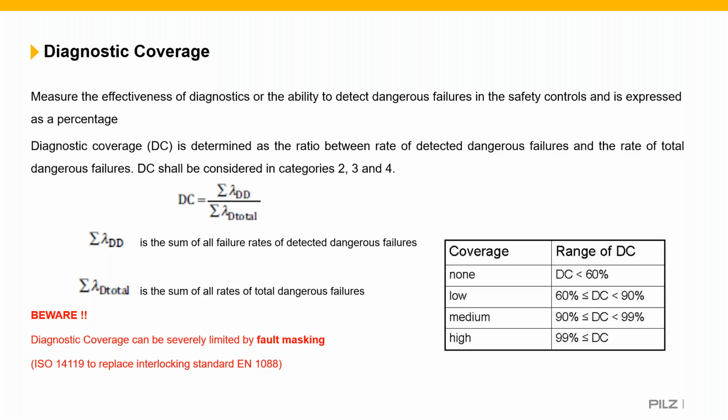So for that specific part of a safety control system, it referenced 13849 and made a statement about what diagnostic coverage you could claim for your interlocking architecture. So that's where everybody went away from series linking fault-free contacts. But we digress, and we'll carry on.